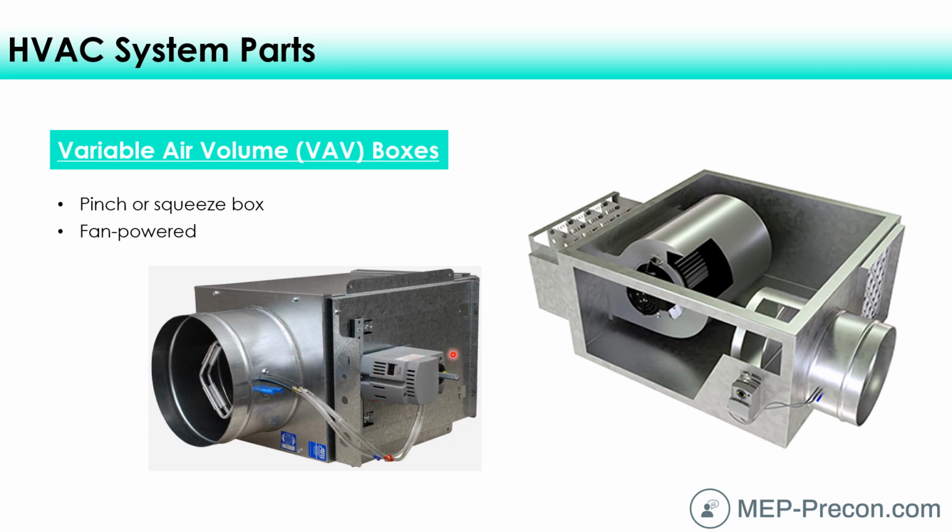The way that these work is there's a thermostat down in the room. That thermostat controls this little damper actuator. And here's kind of a cutaway section. There's the damper there. And whatever the temperature of the air that's coming into that VAV box is, the thermostat can control that damper such that the space is comfortable all the time.